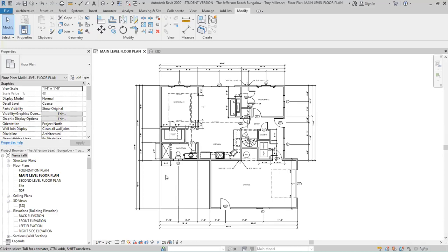Okay, one last thing that we want to do is we want to add some building sections, detail sections, and some interior section callouts or elevation callouts. So if you're looking at the plan here, you can see we have these building sections. A building section, by definition, shows a vertical cutting plane that goes all the way through the building.